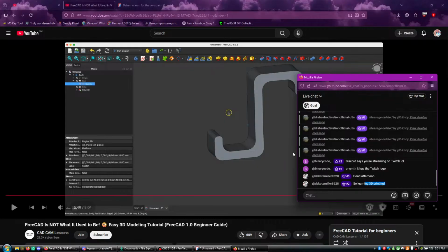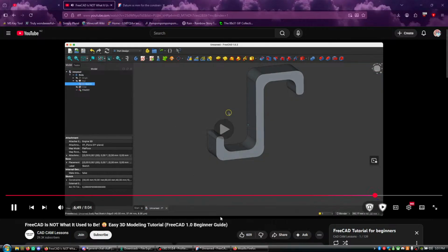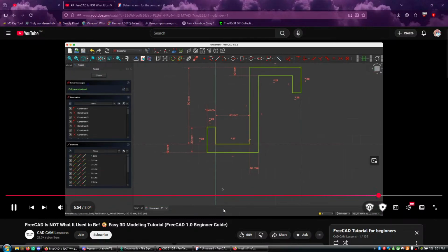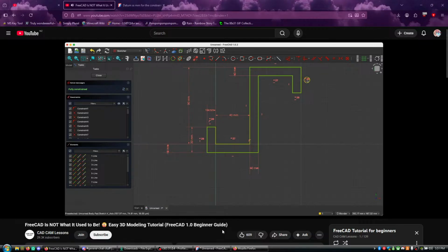Okay, so you can change the sketch and it auto updates. That's actually kind of nice. To change something, we simply go to edit the sketch and introduce changes within the sketch. For instance, in this case, I would like to remove this equal length constraint. It is constraint number 28. Therefore, I locate this constraint on the constraint list, right-click, delete. The constraint has been removed.